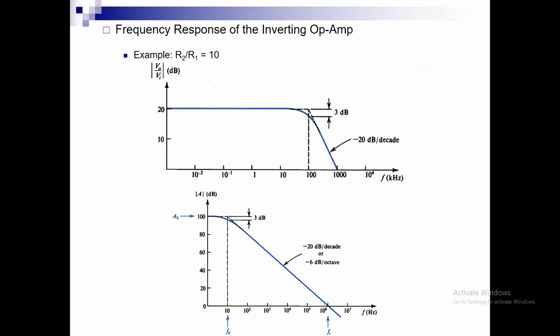طيب, so let us now, okay, if you notice here, what has he drawn? He drew for me the low frequency gain of the new circuit, and he showed me where the new 3 dB frequency is. So what happened here? I start with an op-amp with an infinite gain or very large gain, 10 to the 5 volt per volt, right? I end up with an amplifier that has lower gain, but it has higher bandwidth. So هون بصير كأنها trade off.